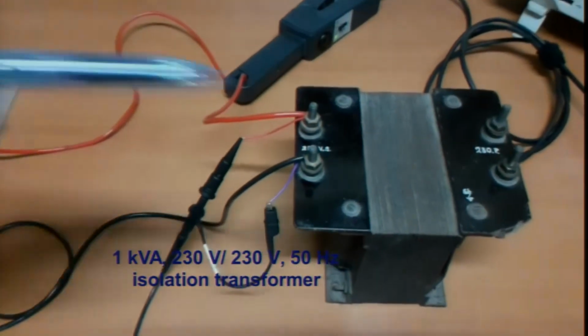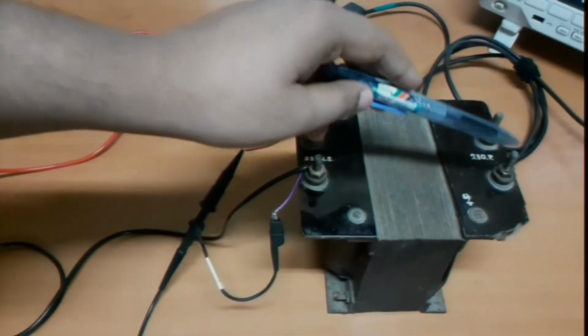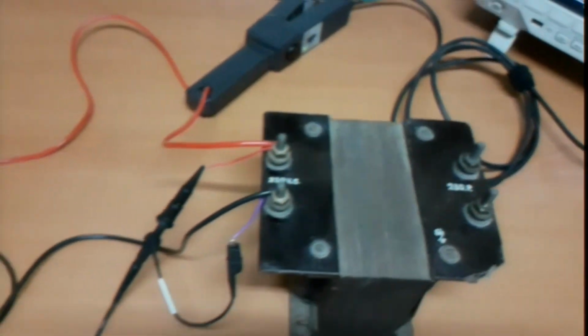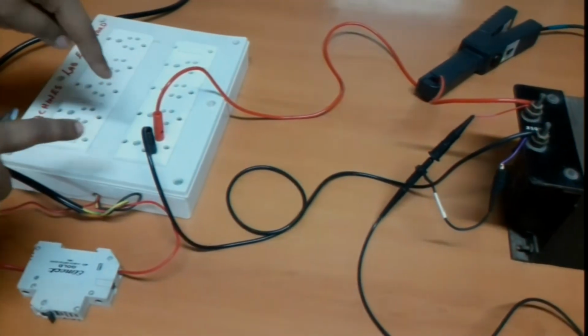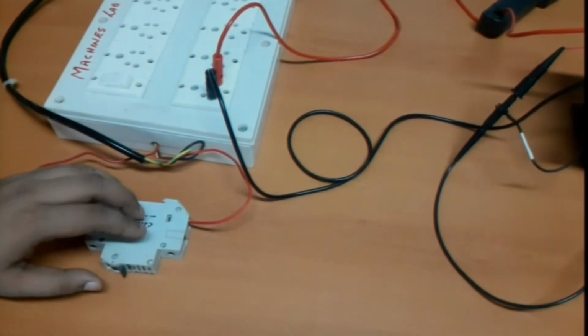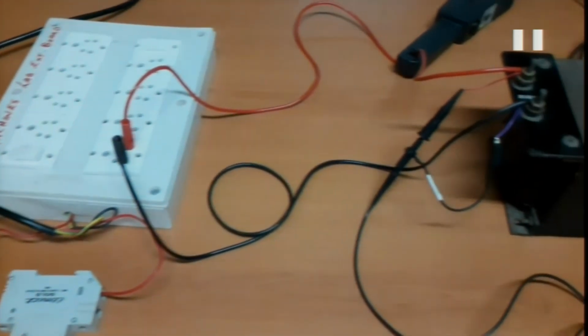What we are going to do is apply a voltage which is equal to 230 volts or thereabouts on this inductor. I call it an inductor because the secondary is kept open. It is being shown that the inductor is open circuited, and this is connected to the laboratory power supply, which is 230 volts, and what we are going to do is just switch it on at some instant. And remember, can we pause for a minute?